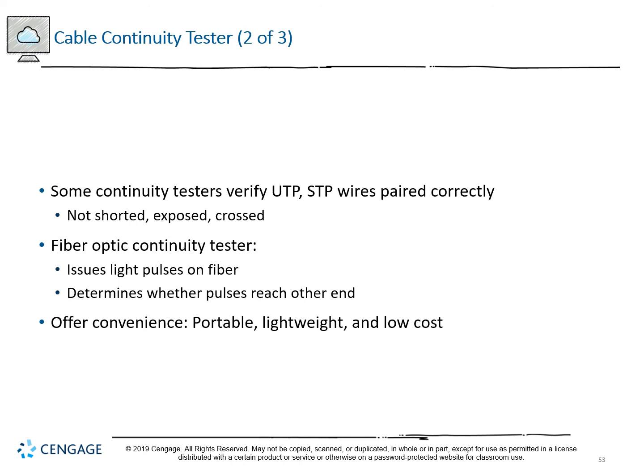I will save you some money. You don't have to go get a fiber optic continuity tester. You just need a really high intensity LED mag light. Essentially, I usually use mechanics gloves. So you'll take a mechanics glove, cup your hand, put the fiber in the bottom of your palm, shine the flashlight in the top, and then have somebody looking at the other end, usually again with their hand cupped. If they can see the light flashes, that means that the cable has continuity.